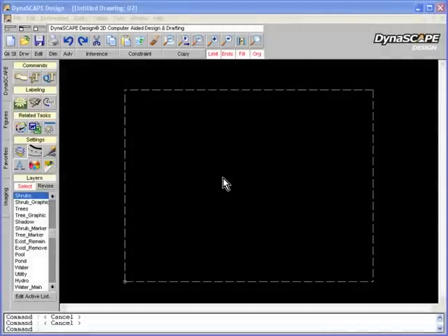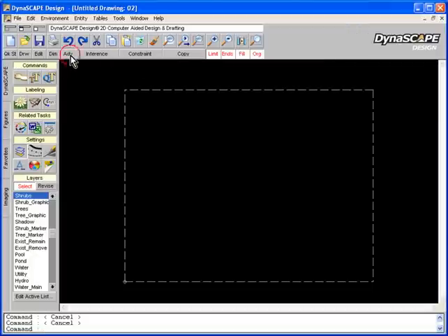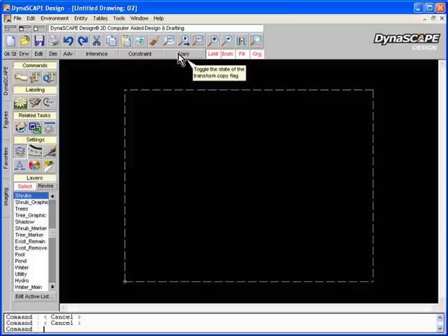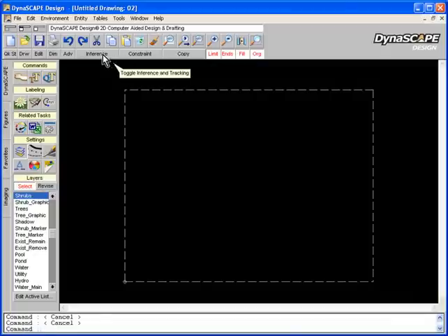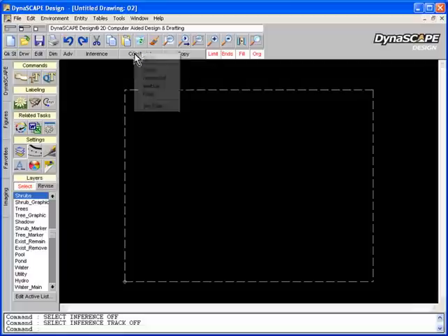It's also important to know the position of the buttons on the toggle bar. The toggle bar basically is this bottom row of buttons here. The first 5 open and close toolboxes. The next 3 are probably the most critical as far as using them while drawing or editing, in that you need to remember the position of them, whether they're on or off, or what the settings are at. We're going to go through these a fair bit.